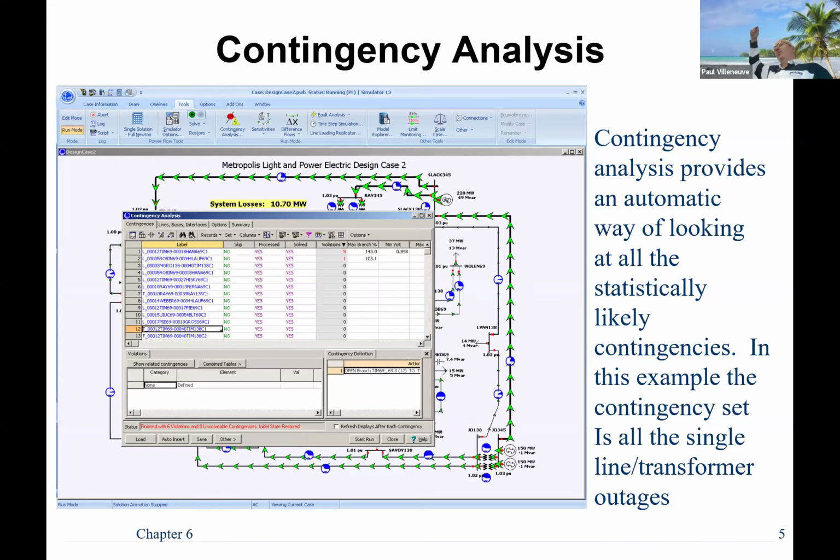And it'll go through and it'll modify your Y bus and your power balance equations for each of those separate contingencies, and then come back and spit out a result to say, hey, everything is still good after this, or no, it's not. So you can do contingency analysis with Newton-Raphson load flow, but you got to do it in advance. You can't just do it at a moment's notice.